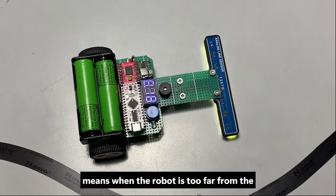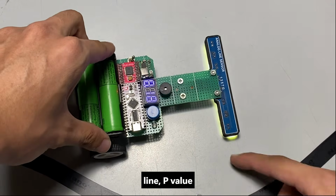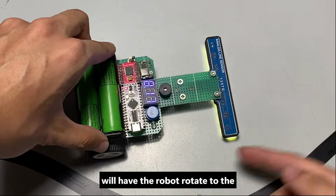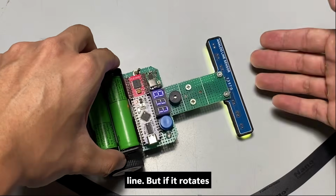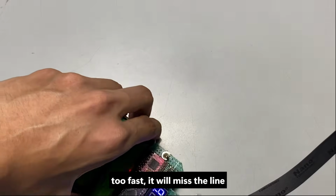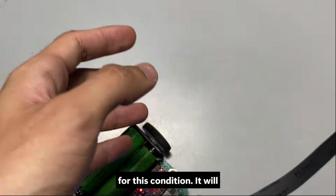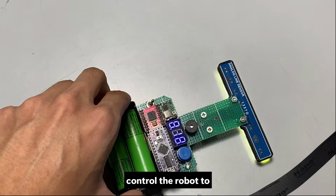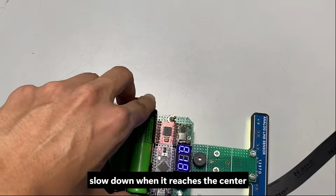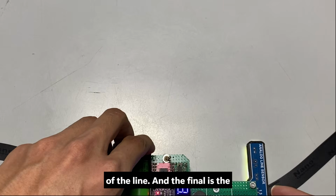When the robot is too far from the line, the P value will make the robot rotate to the line, but if it rotates too fast, it will miss the line again. So the D value is used for this condition. It will control the robot to slow down when it reaches the center of the line.